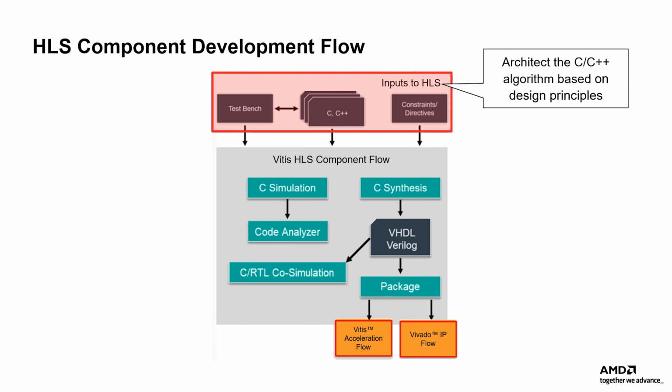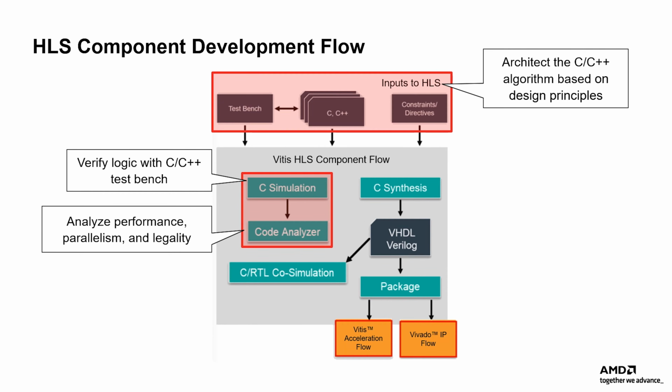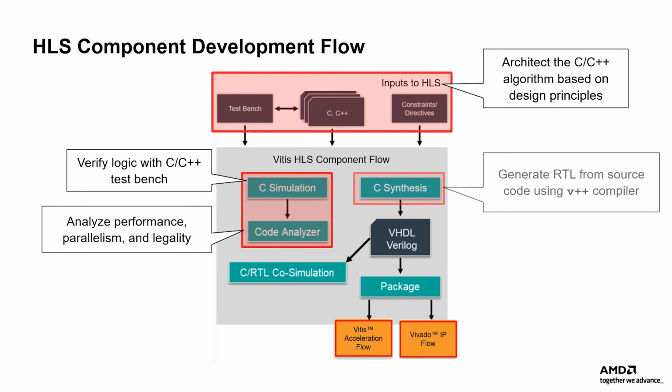Architect the C++ algorithm based on design principles. Verify the logic of the C++ code with a C++ test bench. Analyze the performance, parallelism, and legality of the C++ code. Generate the RTL from the source code using the V++ compiler.